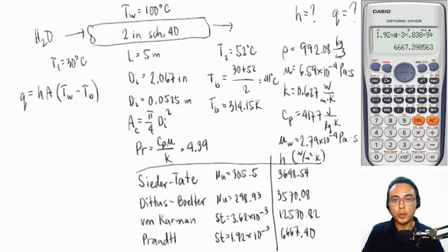Remember, the bulk temperature is the average temperature of the water while it's staying inside of the pipe. Now, since we know the inlet and outlet temperatures of water, we can also use the equation Q is equal to mCp delta T to determine the actual heat that is transferred to the water. So we write Q is equal to mass flow rate times Cp times delta T. In this case, delta T is the change in temperature of water. This now becomes T2 minus T1.